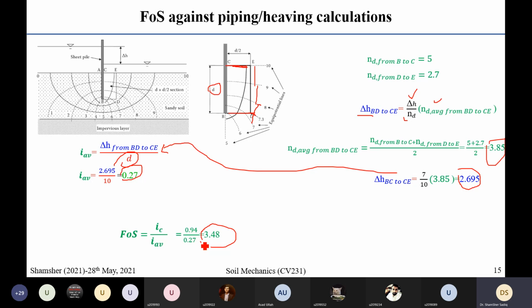So, as a geotechnical design engineer, when you are working on a design problem, for the safer side, you have to design for a factor of safety of 4 to 5, not for 1. Because there can be many uncertainties during construction, during seepage flows. So we always design conservatively. Any question on how I solved this practical example? Mehran, is it clear? Yes sir.